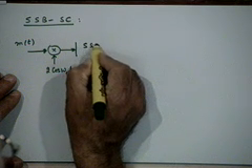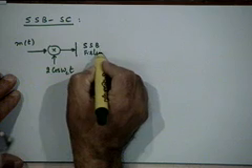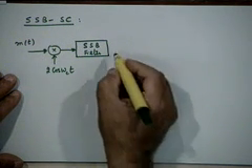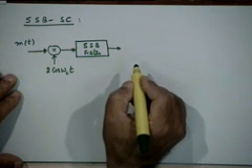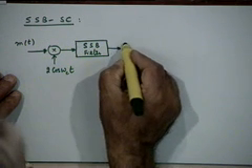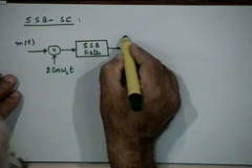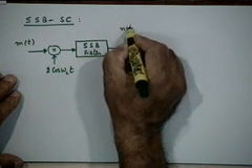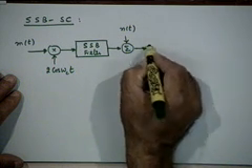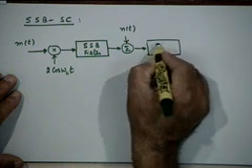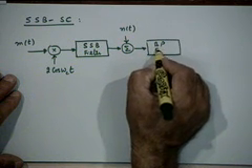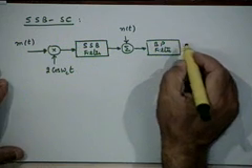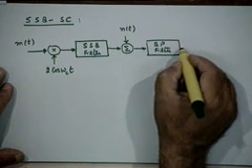And after this you will have the SSB filter, which will remove one of the two sidebands. That is what you will finally transmit over the channel. The channel once again is going to be assumed to be ideal, and the only effect that is of interest to us is the presence of noise n(t). At the receiver you will have a band pass filter with a center frequency of omega_c.